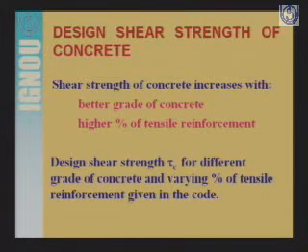In your IS 456 code, you will find a table in which design shear strength, tau c, that we generally say, is given against the percentage of tensile reinforcement as well as the grade of the concrete.